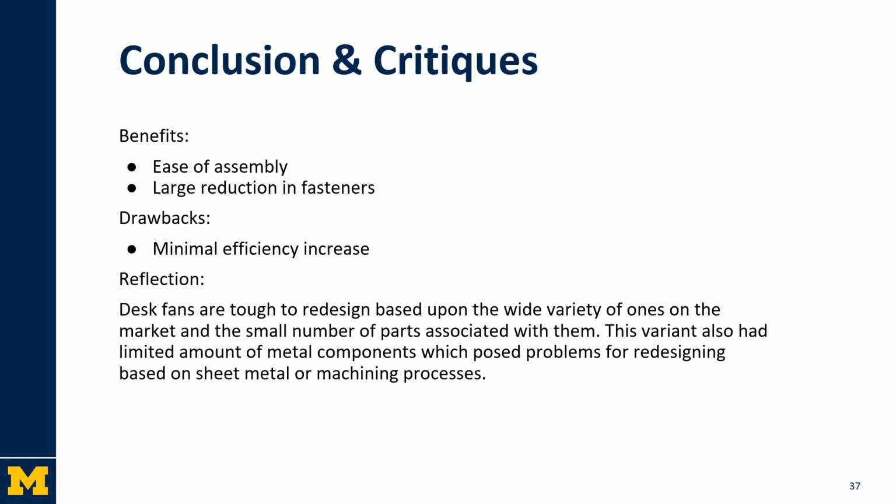In conclusion, the benefits that we came across was we were able to greatly ease the assembly of our fan due to our large reduction in our fasteners. The drawbacks was we had a minimal efficiency increase with our redesign. Reflecting on the desk fan, it was a tough redesign based on the wide variety on the market and the small number of parts associated with it. And the variant that we chose also had a limited amount of metal components, which posed problems for our redesign using sheet metal and machining processes.